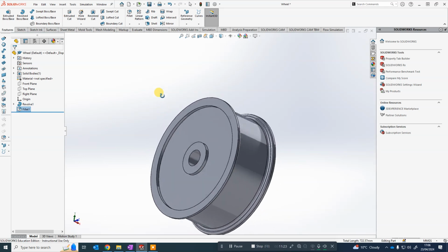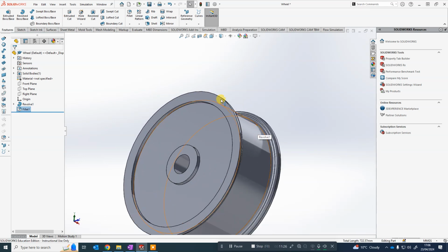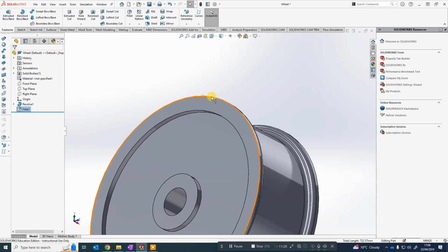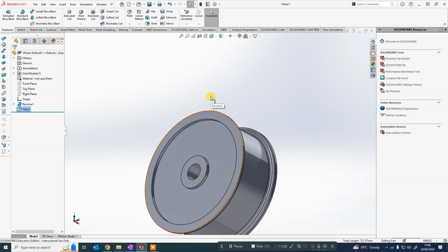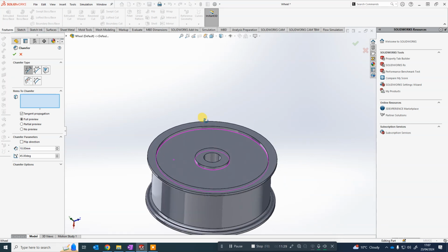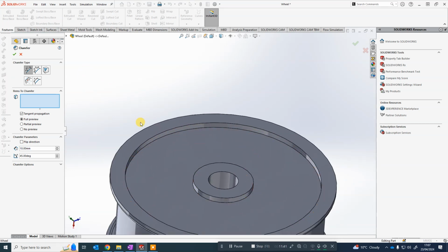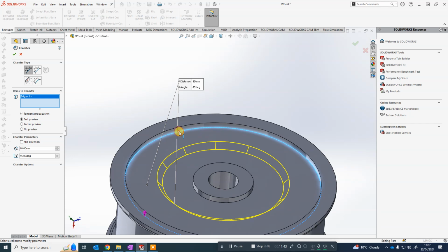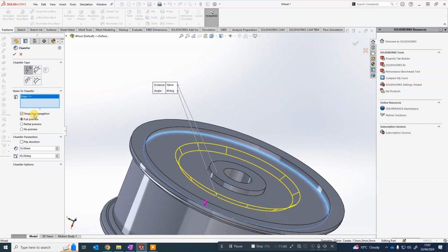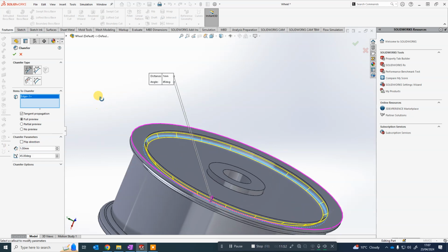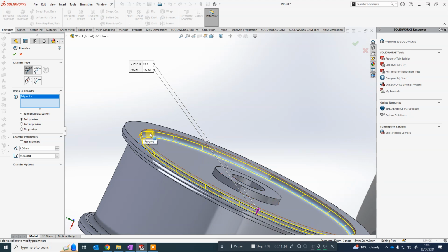Okay. You can add some fillets elsewhere. Generally, the top edge of the wheel is sharp, like that, so it looks cleaner. It's down to you. You might also want to experiment with chamfers. So again, if you click the drop down and choose chamfer, rather than a curved corner, that will give you like an angled corner. So I'm going to put a chamfer in here. Again, making sure full preview is chosen. Now, my chamfer is so big that it's done a weird effect. I'm going to change it to 1 because I want my chamfer just sort of near this edge here.